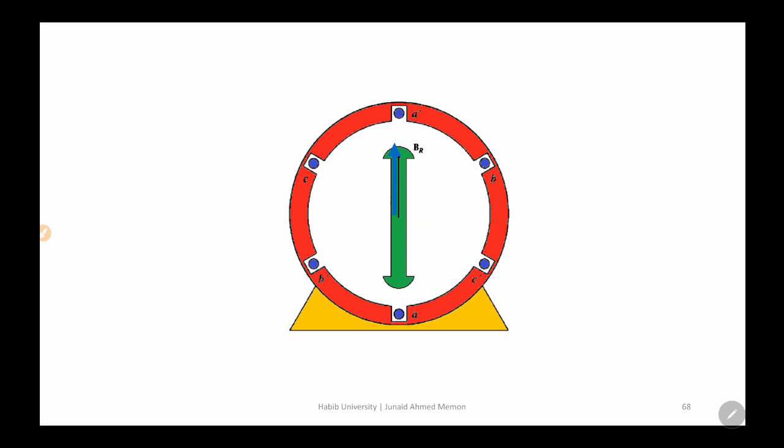Earlier, when we ran the animation, we assumed that the rotor didn't have inertia, or you can say that the rotor was already rotating at the synchronous speed. Then at that point your rotor will be following the stator's magnetic field. But if your rotor is at a stationary point, and the rotor usually has a load connected with significant inertia, then when your stator's magnetic field varies, your rotor will not be able to catch up because of the inertia. It will slightly turn along in the direction of the rotating magnetic field, but after a certain time, as you can see in this particular snapshot, the rotor magnetic field is completely opposite to the stator's magnetic field.